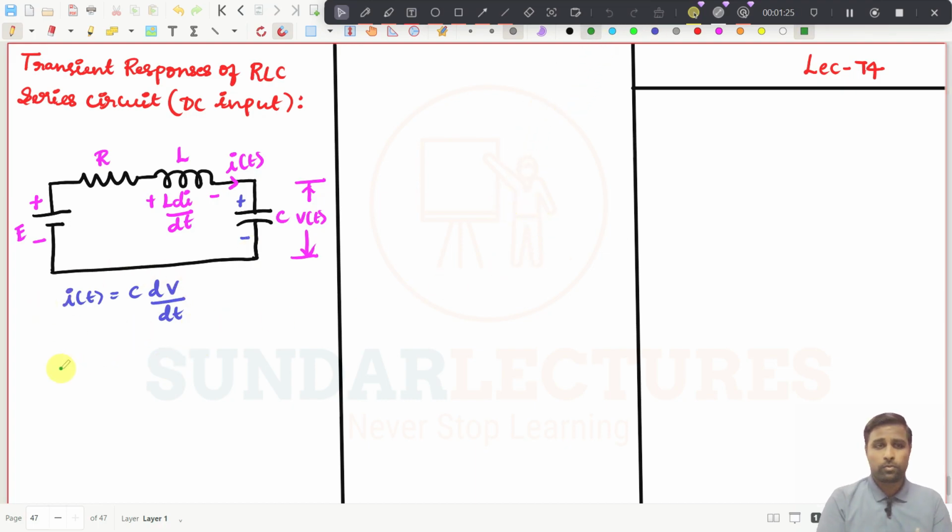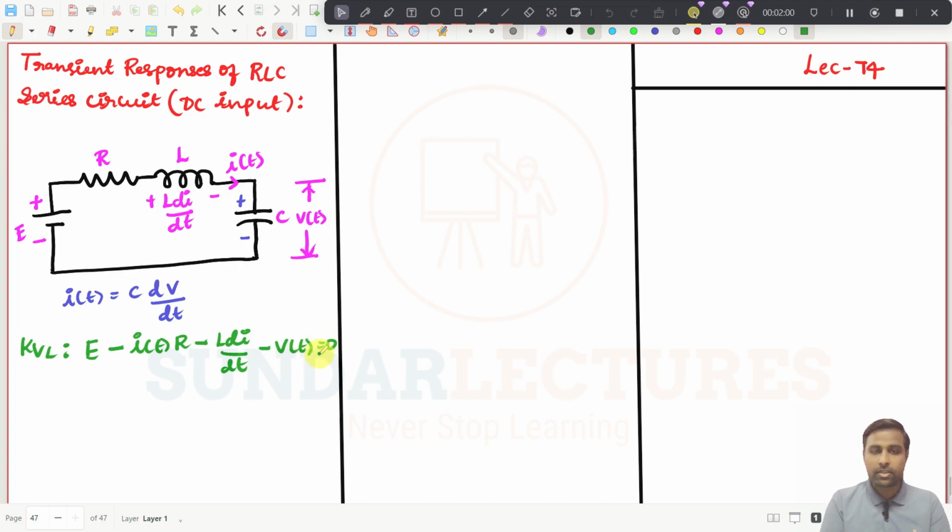Now we are going to write the KVL expression for this circuit. The current direction is like this, so going from minus to plus it is plus E, and the current is going in the same direction as we are going, so it will be minus I of t into R, and then moving from plus to minus it will be minus L into di by dt. We have already seen that the voltage across the inductor is L into di by dt, and then minus V of t, which is equal to 0. This is the expression by KVL, right?